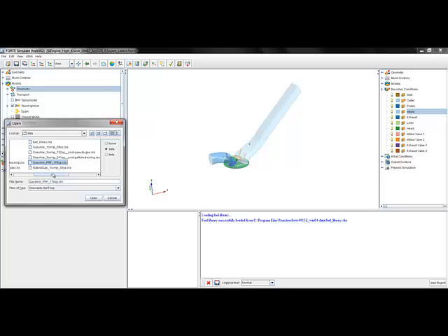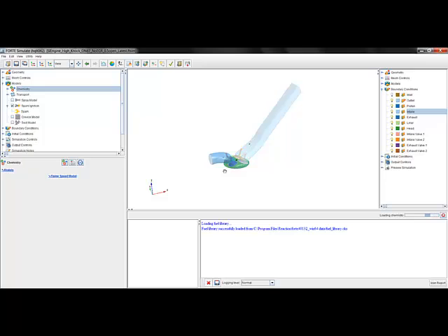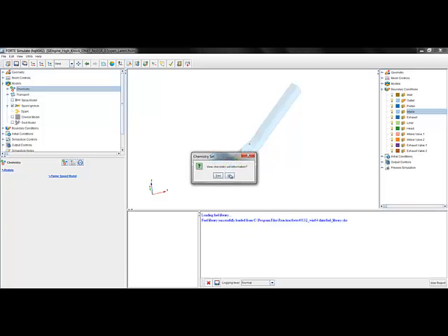The PRF mechanism in this case has 178 species, which is considered quite a large chemistry mechanism for most CFD tools, but is considered an average size chemistry mechanism in Forte. This PRF mechanism has been reduced to predict knocking in engines, so it includes the low temperature chemistry that is required to predict the autoignition of the end gas. So we could just click open to import that chemistry mechanism, and then we have the opportunity to view it.